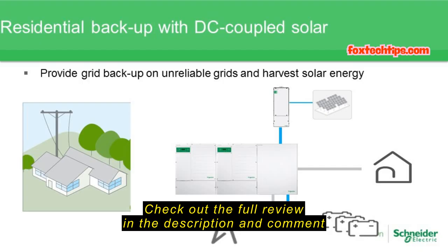Just because you have an event, an event being like a big storm or something like that, doesn't necessarily mean that you're going to lose power, but you should be aware of those large loads. Even at 50 amps, you think about what 50 amps is kilowatt wise, that's a very, very large system. At 230 volts, 50 amps, we're talking about over 12 kW. And so that's why you'd have a pair of inverters in this example to cover all the loads inside the home. But think about, not that we always have 50 amp loads, but let's say we had half of that, 25 amp loads at 230 volts. Suddenly that's a very large amount of power being consumed off of that system. So the question is, is the customer really interested in investing in that large of a battery bank to cover those loads for whatever their expectation is?